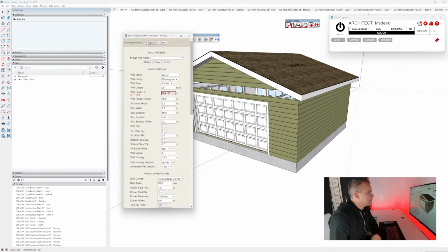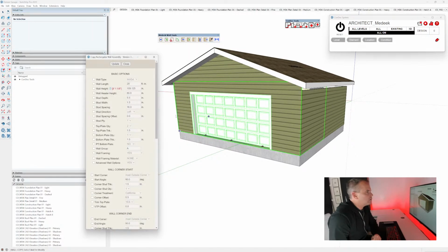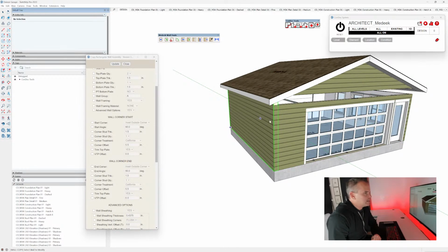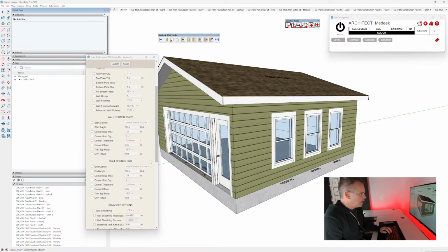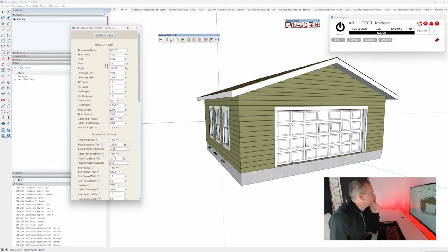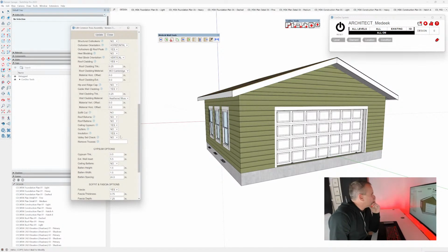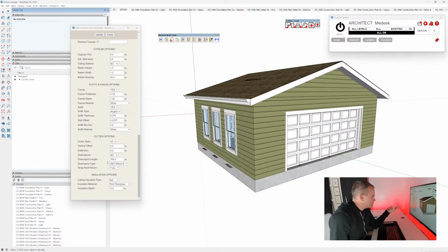And this wall assembly should be 109.125, and update that. All right, and now we'll close this and we're going to use this wall sample tool to sample the height like that. And then we can go around and just say yup, yup, and see how this one's yup, like that. We'll close that. Also, I want to right click and edit our truss assembly. And when I go down here to our gutters, let's turn on those, yes, update, like that. So we get gutters. And then now we have gutter options. We have downspouts, yes, update, like that.